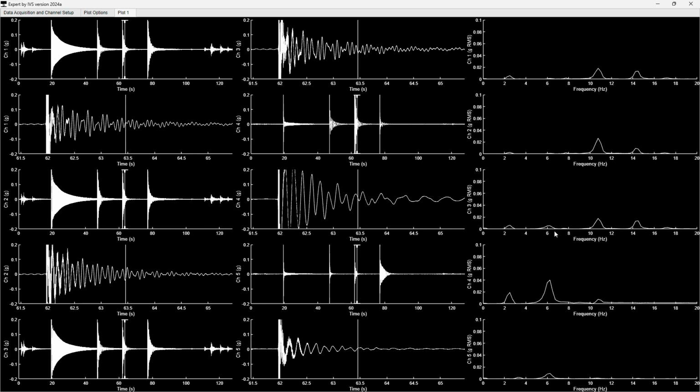And yeah, when I did the impact in the center of the plate, the horizontal impact, it didn't excite that one because there's no displacement at that location for that mode shape. But if you do the horizontal impact on the outer corner, it does excite that mode shape. And that's, I guess, an important lesson for when you do impact tests. You can miss important natural frequencies or mode shapes if you do the impact in the wrong location. So a good rule of thumb is either to impact slightly off center or on the outer corner, or maybe impact in two locations.